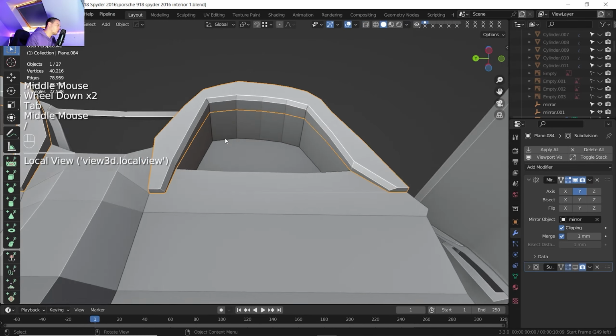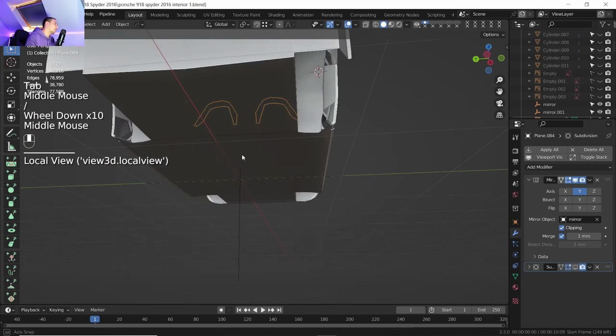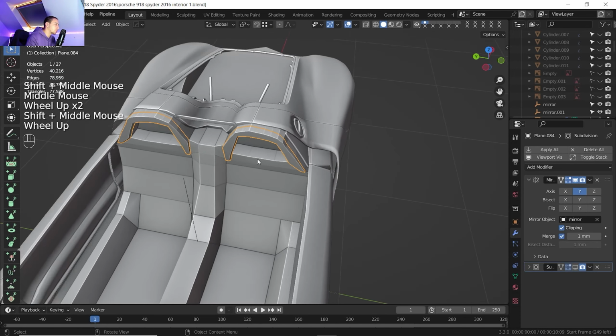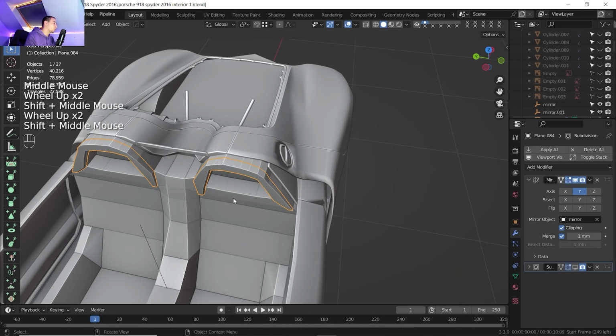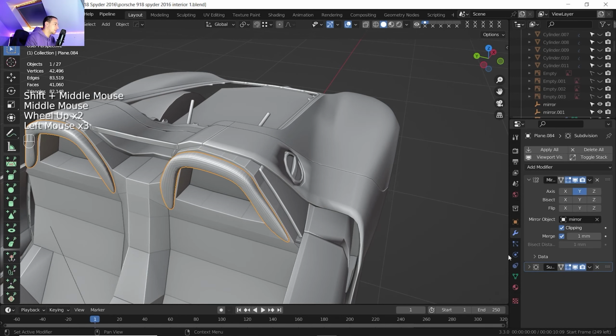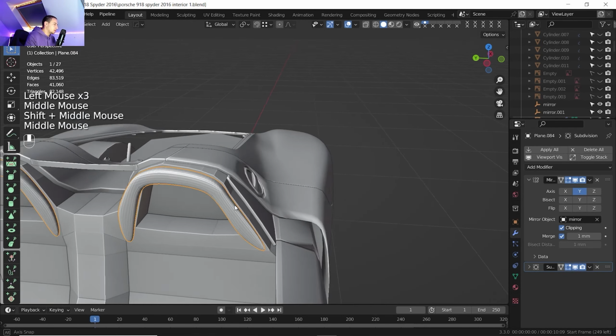It's just much better. The triangles, let's say, are fine. If you don't have a lot of triangles, it's just fine. You can let one triangle or two in the mesh to be there. But n-gons, when you subdivide them, they mess up the whole area. It's not subdividing as you are expecting it to.